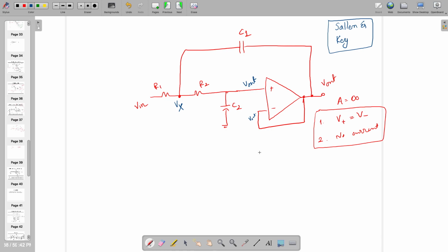So are you going to write down two or three equations? How many equations are you going to write down? Because I can solve it in one equation, by the way. How do you find out one equation only? Current at that node. Excellent. At this node, because it covers all the nodes.